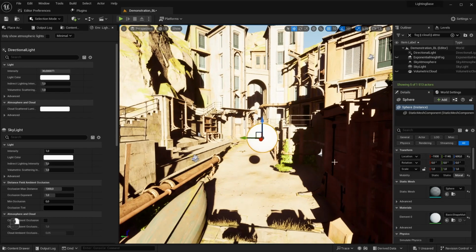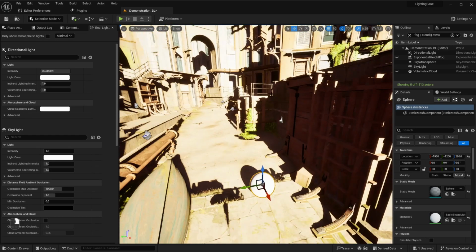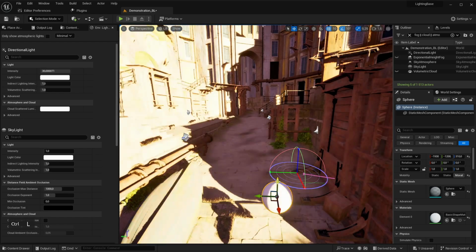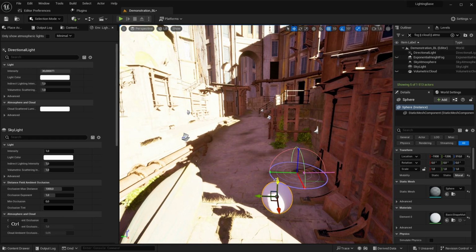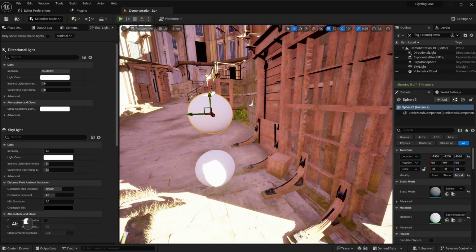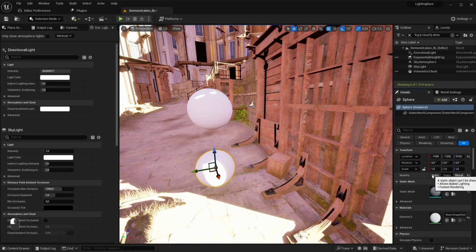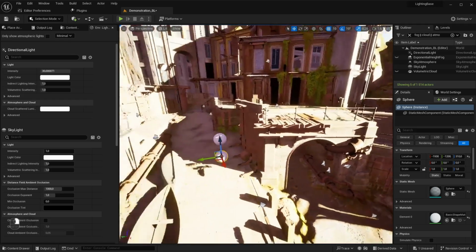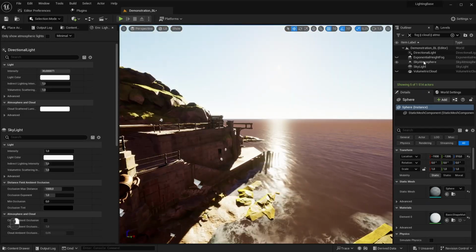For that, let's keep this object here. Let's actually change the light angle a little bit, so maybe it's somewhat in the shadow. And let's add a copy of this, and let's turn the bottom one to be static so we can play around with the differences after we have baked the lighting. Before we get to baking the lighting, let's take a look at the sky atmosphere.